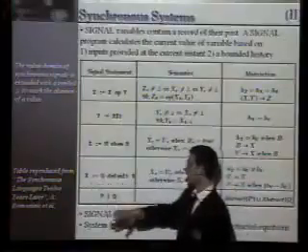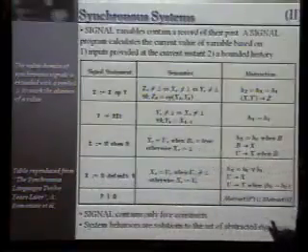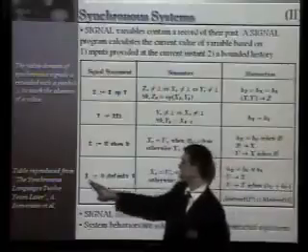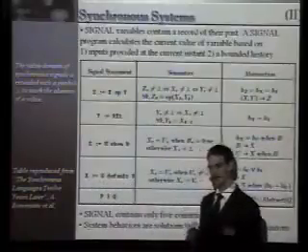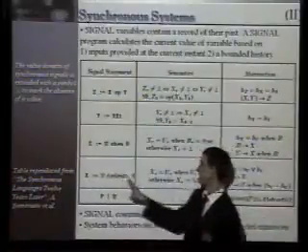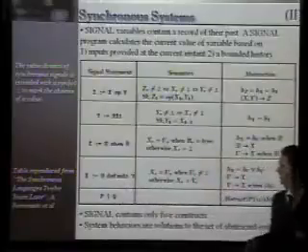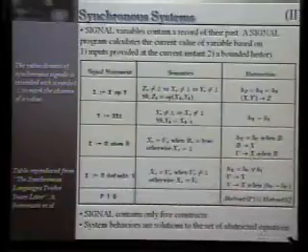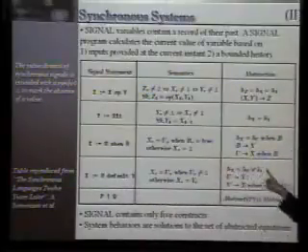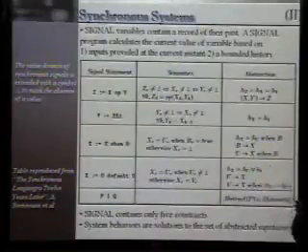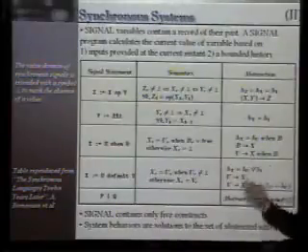Okay? And then there's one more interesting one, which is the merging of two signals. So this says that x can take on the value u if u is present. If it's not present, give it the value v. Okay, so this is set here. In this case, the clock of x is the union of these two clocks. The events when u and v are present, you union all of those times together. That's the events.